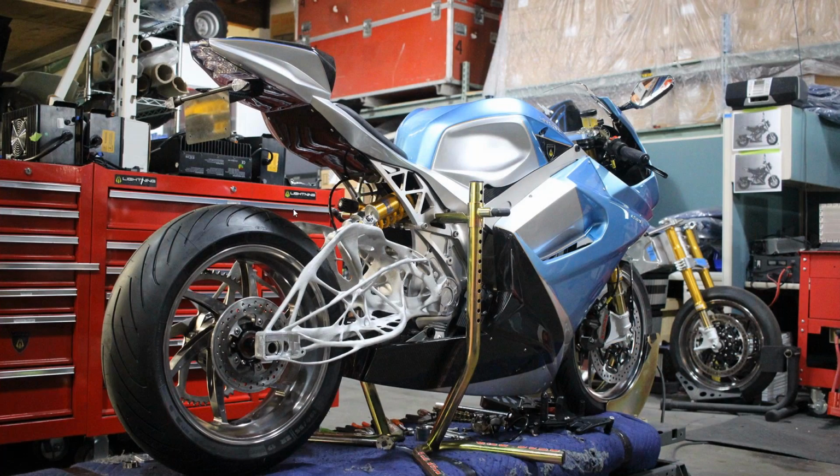So the next thing I'd like to talk about is how to actually set up the design space for generative design. If we look at the swing arm of this motorcycle, it's a very complicated generative output. But when it comes to the setup point, it's actually very easy. So within generative design today, there are only two types of geometries that we need to create, extract, or take out of our existing assembly to run a generative design solve. Those are preserves and obstacles.